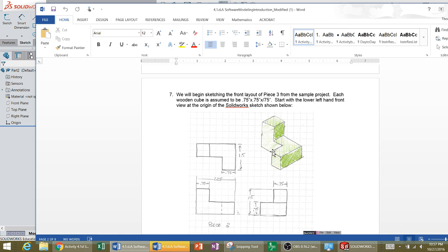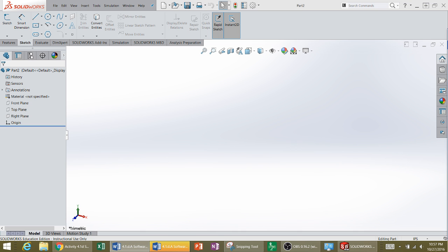So here's our drawing that we're going to draw. And in solid modeling, we always start out with a sketch of some sort. And to sketch, you can think of it almost exactly like sketching on a piece of paper. So when you tell Solidworks to start a sketch, it's going to ask you where. And we can really sketch, if you think about it, in one of two ways. We can sketch on a plane, or we can sketch on a surface.